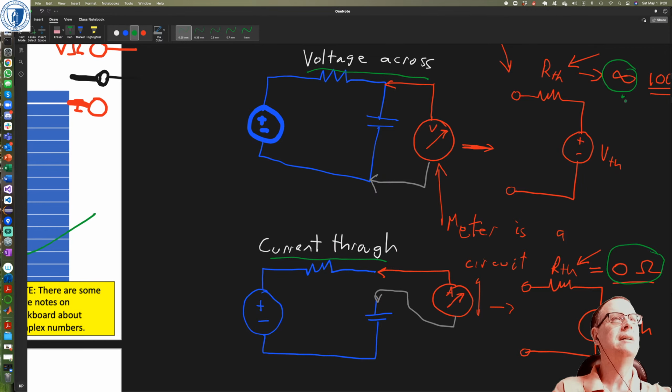But to change from high impedance to low impedance just by the push of a button would be quite expensive to do. So the way they do it is they just have separate terminals. And the mistake you will make when you try to do this physically is you will try to measure current.